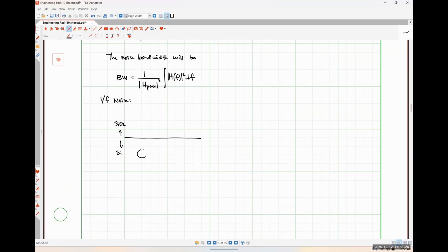So down here in the silicon space, we have extremely well-ordered periodicity, all of that kind of good stuff. Except that at that material interface, we have, from the standpoint of crystallography, a defect.